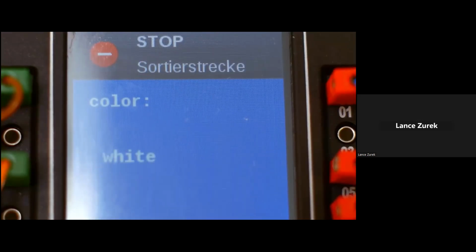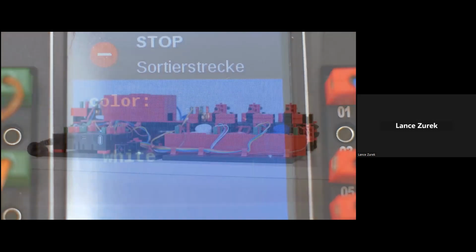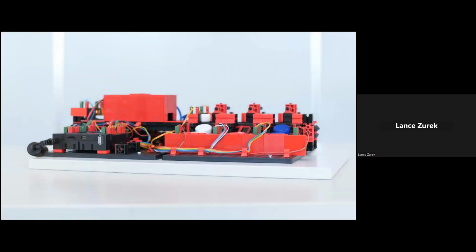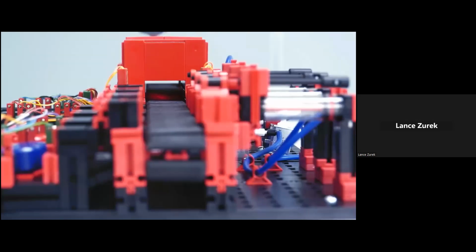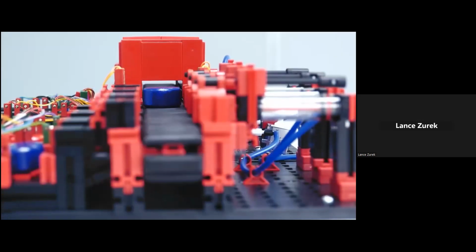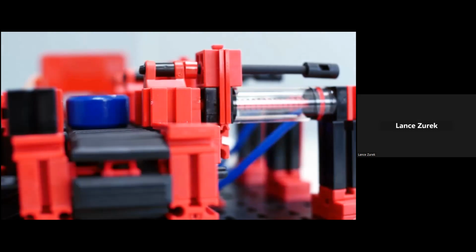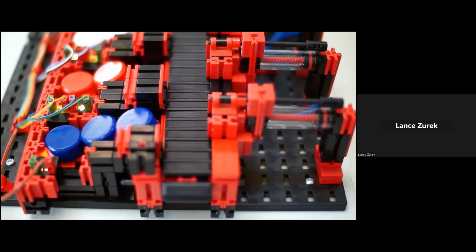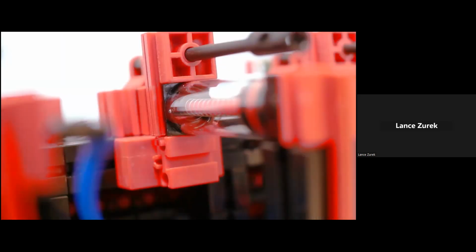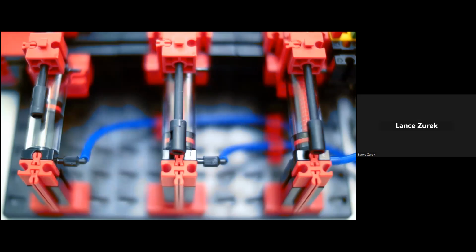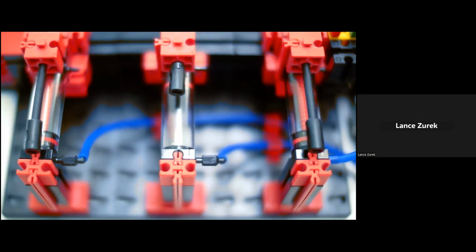Now, as with the models we've looked at before, the standard 24-volt version has a relay board for motor polarity reversal and both a multi-pin connector, 34 pins with a grid of 2.54 millimeters, as well as additional PCB terminals with push-in connections for all inputs and outputs. Again, you do need to provide the PLC and the program. And there is a limited edition 9-volt version, which comes pre-wired to a pre-programmed robotics TXT controller, and in that case, one 120-volt power adapter is required.